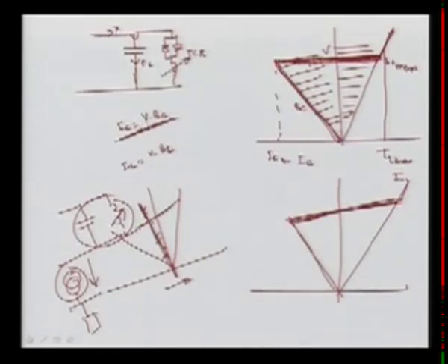Regulation, that is a droop or slope, tends to enforce automatic load sharing between the static compensators and other voltage regulation. Due to the coupling reactance, the voltage drop is normally 10 to 20%, but the slope reactance is typically between 2 to 5%. So we don't want much slope. This slope is still not desirable, so we try to go for the minimum slope that is required, so that we do not have hunting, and at the same time we can have stable operation.